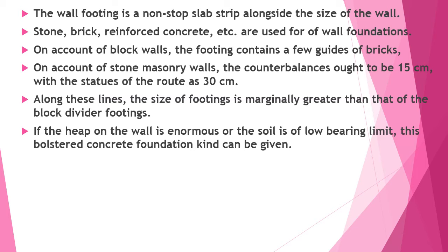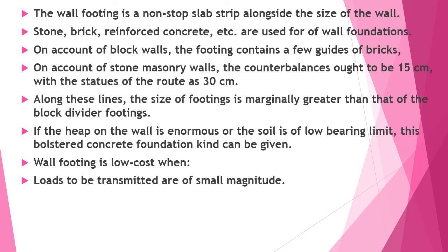If the load of the wall is large and the soil has low bearing capacity, this reinforced concrete foundation type can be provided. Wall footing is low cost when the loads to be transmitted are of small magnitude, positioned on dense sand and gravel.